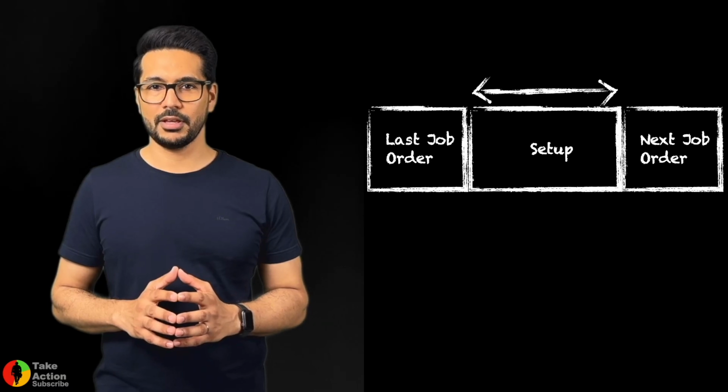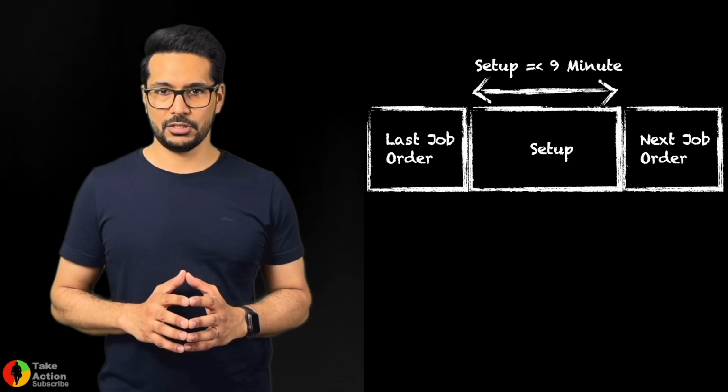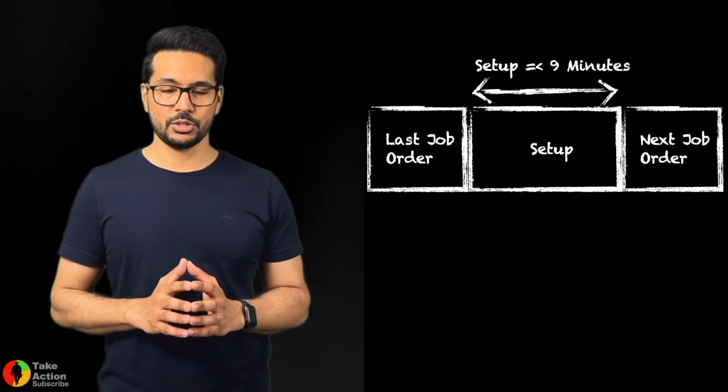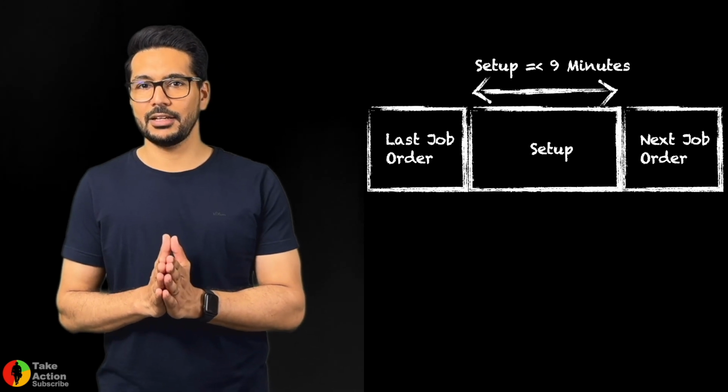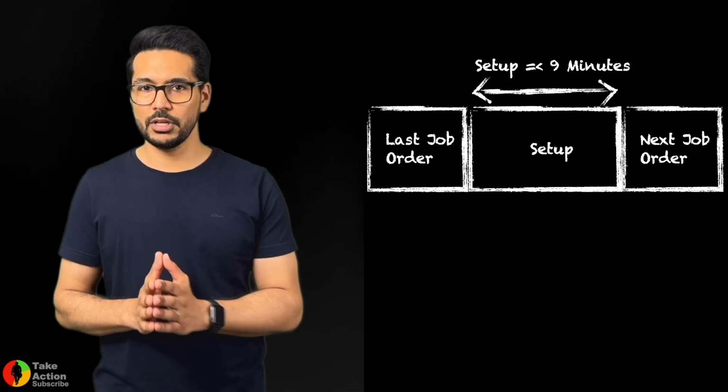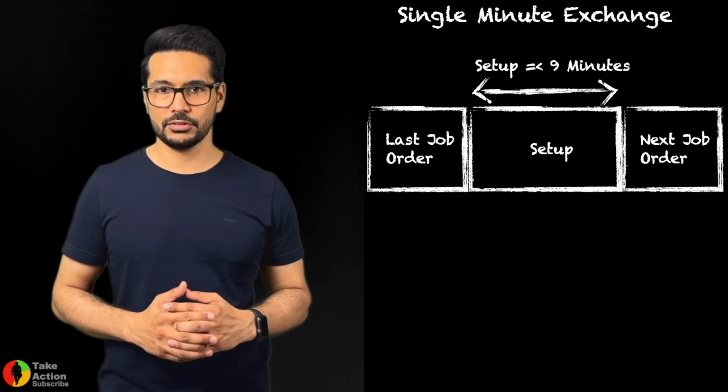Single minute exchange of dies. It doesn't matter if your setup time is 4 hours or 2 hours 20 minutes. The aim of this method is to achieve the setup time in less than 10 minutes, so 9 minutes or less, so that we achieve this in single digit. That's the name of this tool, single minute exchange of dies.